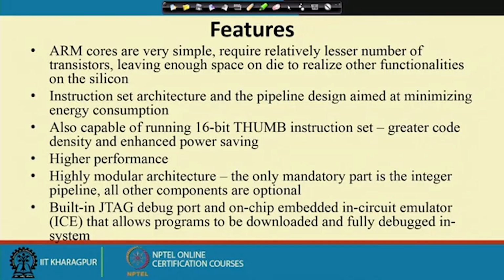Modular architecture. Modular architecture means that the entire design can be divided into sub modules, and as per your requirement you can say that you need this module or you do not need that module. For example, take security. The advanced versions of the ARM processor even have security modules built into them. If you do not need the security modules for small embedded applications, you do not put those modules into your design. Similarly, there are modules responsible for signal processing jobs, where the DSP algorithms will run better.